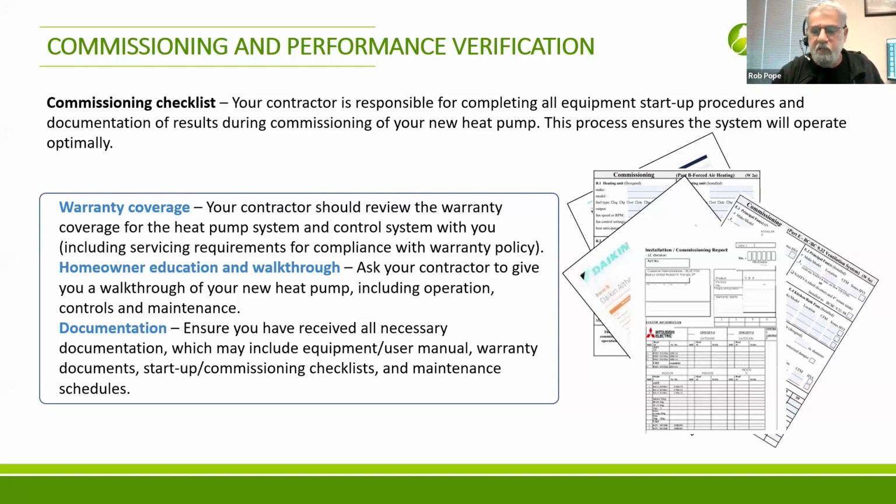And you want a commissioning report. A lot of manufacturers require startup checklists that you have to go through, and then there are industry checklists you can get. In other words, if I'm a homeowner and I'm getting a system installed, I want to hold out my hand and say, let me see the paperwork that you've done your startup and commissioning properly. There's no lack of forms from the manufacturer directly or from the industry that are easy to access. As you can see to the right, there's tons of them. There should be a commissioning report.